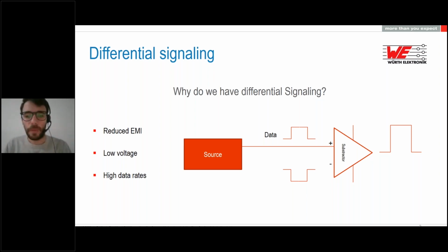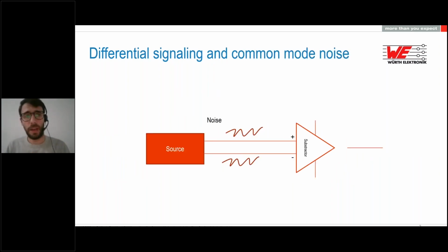If we have any kind of electromagnetic interference or crosstalk, as we said, from the other parts of the device or the design, or from the traces, this noise that is coming from the outside affecting our design affects both the positive and the negative sides. So this noise is distributed, and then we have a kind of balance. This also helps in reducing the effect of EMI affecting the design. That's why we normally use differential signaling. What's the problem that we could have with differential signaling?